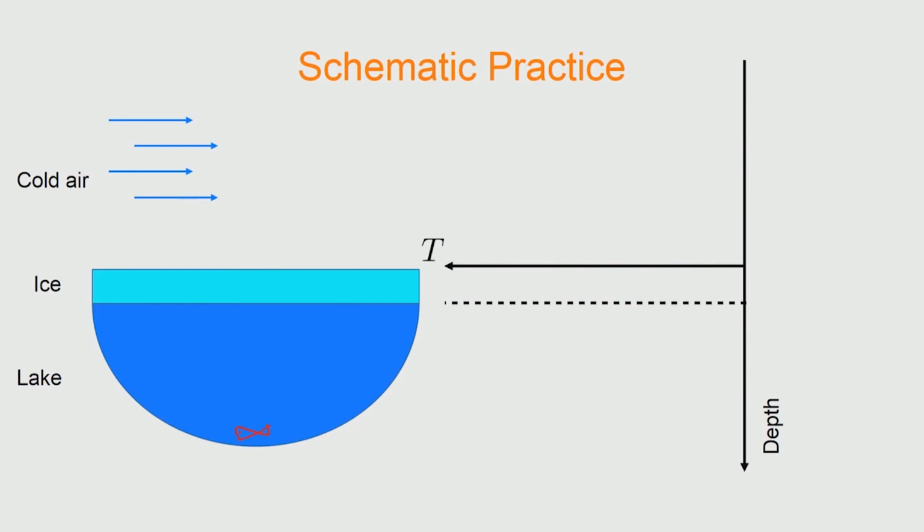Now how do we go about drawing the profile here? The way you draw the profile is identical to the way you draw in the furnace problem, because you do have different layers of different thermal conductivities, and you could start off by fixing some temperatures that we know. We know that cold air, unless it is much lower than 0 degrees centigrade, will not lead to formation of ice. So the temperature must be very low on the cold air side.